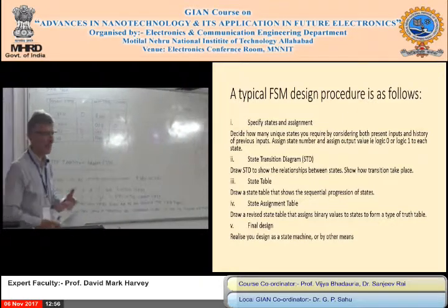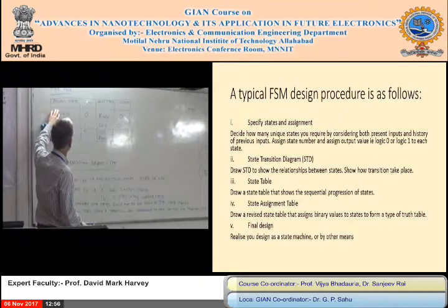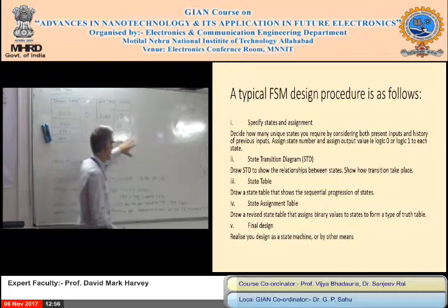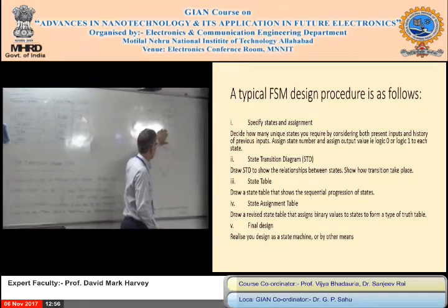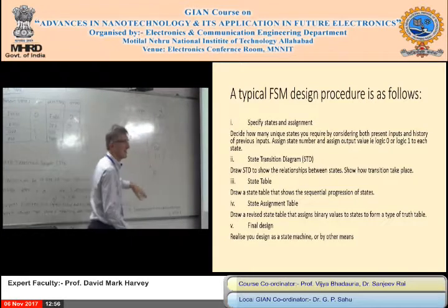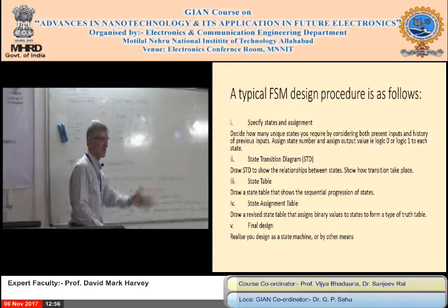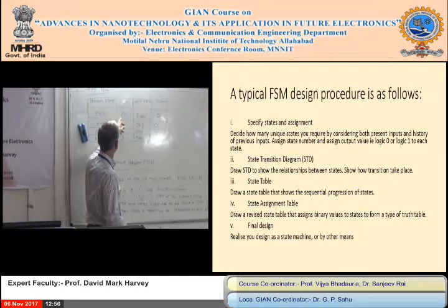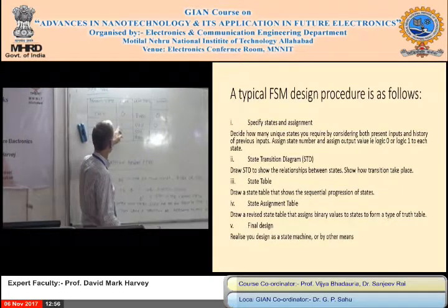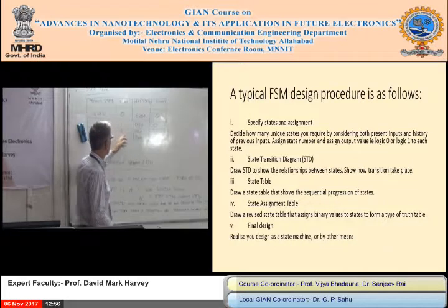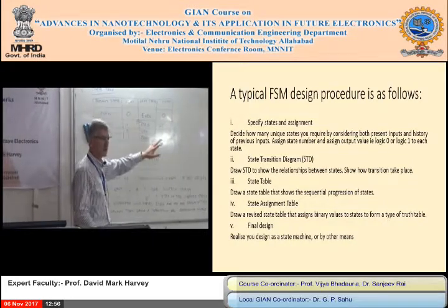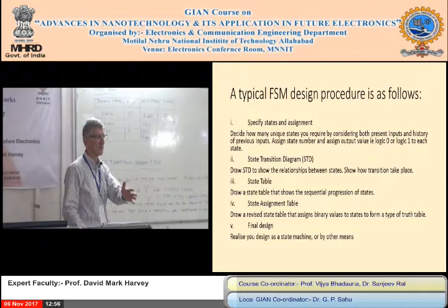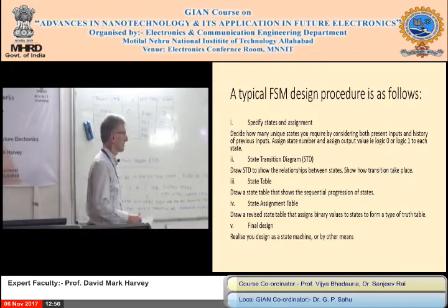So what we're doing, present state, this is the present state output. Okay? So if we're in even state, the output is always naught. If in the odd state, the output is always 1. So we do the clock. When we do the clock, with a naught input, we're still in even. If we're in even, the next state we're changing, going to odd. But we don't change the output till the next state. That's the beauty of the clock. It's clocked through. The feedback comes through the clock.